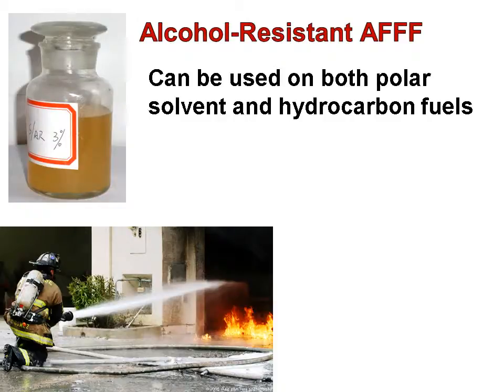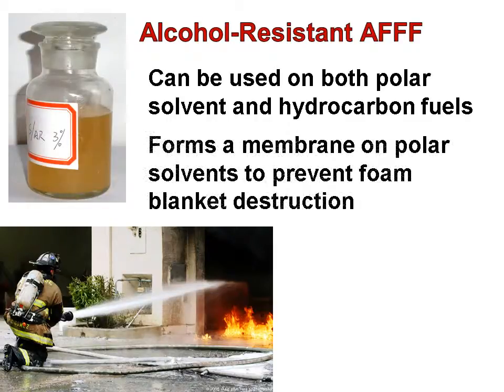Then the alcohol resistant AFFF can be used on both polar solvents and hydrocarbon fuels. It forms a membrane on polar solvents to prevent foam blanket destruction once you have it laid down. It's got a fast flame knockdown and good burn back resistance.